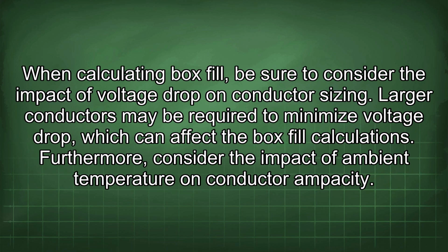When calculating box fill, be sure to consider the impact of voltage drop on conductor sizing. Larger conductors may be required to minimize voltage drop, which can affect the box fill calculations. Furthermore, consider the impact of ambient temperature on conductor ampacity.